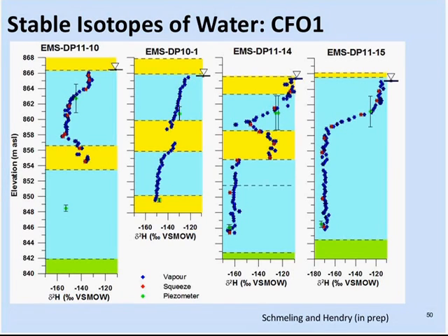But what's far more interesting is how to interpret this. The previous interpretation would have been based on monitoring wells, and all you have are 2 points, one near the top and one near the bottom. Now, if you look at the delta value down at the bottom, this is just showing deuterium, we quickly see that this is glacial water at depth. And so the interpretation based on wells would simply be, it looks like we have pretty close to modern water near the top, and it looks like there's glacial water at depth, and that's about all you can say.